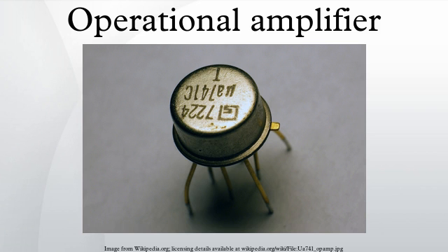Architecture: a small-scale integrated circuit, the 741 op-amp shares with most op-amps an internal structure consisting of three gain stages. The differential amplifier provides high differential amplification, with rejection of common mode signal, low noise, and high input impedance, and drives a voltage amplifier. The voltage amplifier provides high voltage gain, a single pole frequency roll-off, and in turn drives the output amplifier. The output amplifier provides high current gain, along with output current limiting and output short circuit protection. Additionally, it contains current mirror bias circuitry and a gain stabilization capacitor.